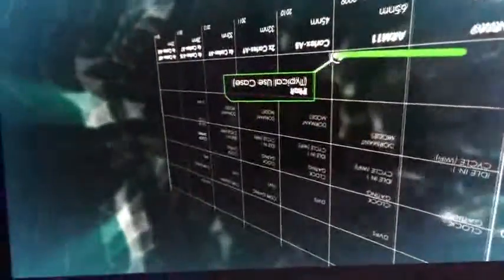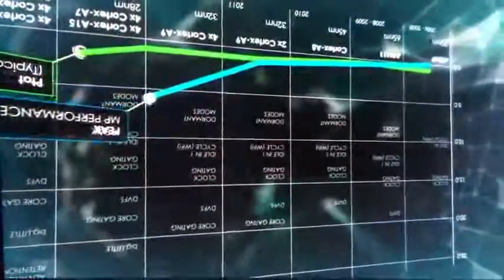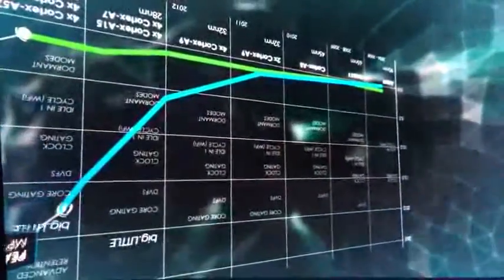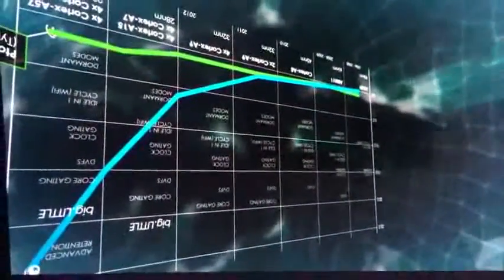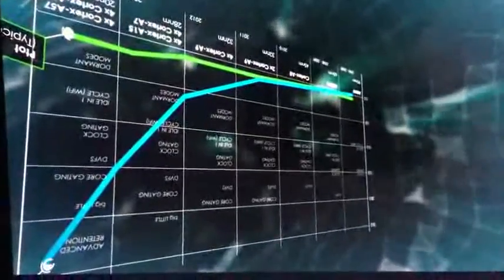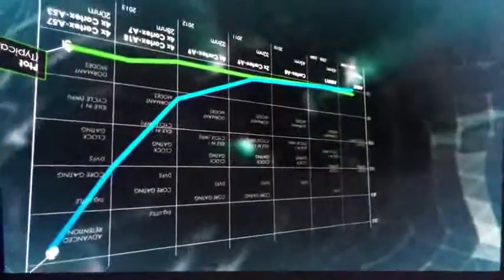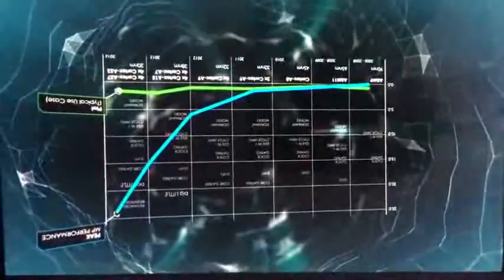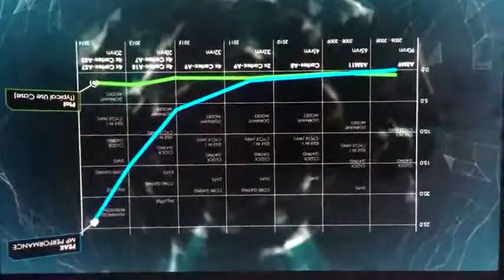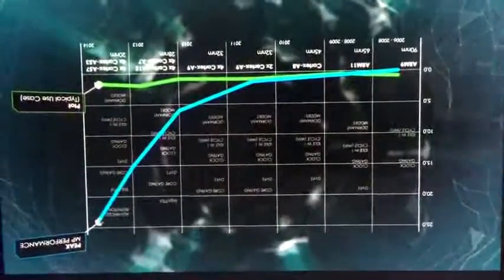Low-power techniques have evolved from clock gating through dynamic voltage and frequency scaling, multiple cores, specialized accelerators, then the rise of GPU compute, and most recently, ARM big.LITTLE processing technology. big.LITTLE is the latest in a series of innovations that have allowed huge improvements in mobile performance within a constant power budget.